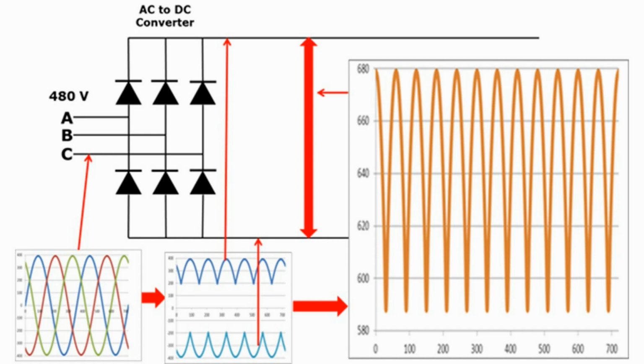The first stage, the converter, is comprised of 6 diodes, which allow current to flow in only one direction, same as a conventional diode bridge circuit. The direction shown by the arrow is the diode symbol. For example, whenever A phase voltage is more positive than B or C phase voltages, then that diode will open and allow current to flow.